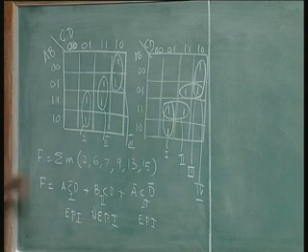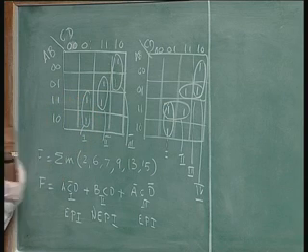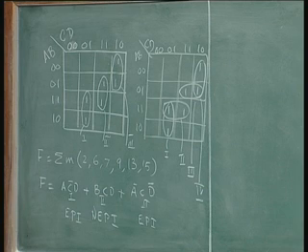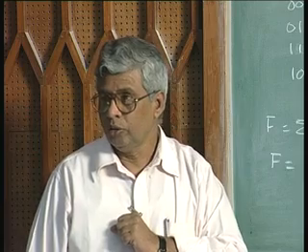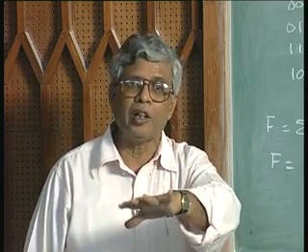For the reason that this one could have been combined with this, I could have made another prime implicant. It is the only way in which I can make a prime implicant, 1 is required, otherwise that 1 gets left out, only then it is an essential prime implicant. We are not talking of the most efficient way here, remember that I am only talking about definitions. Just because it is an essential prime implicant does not mean that it will be the most efficient way of doing it.